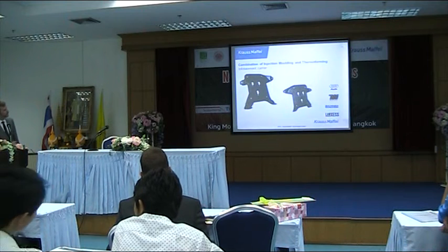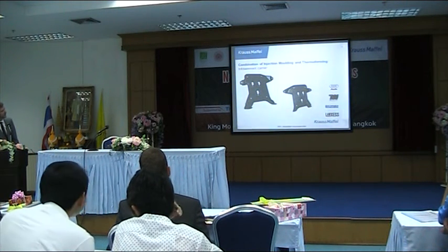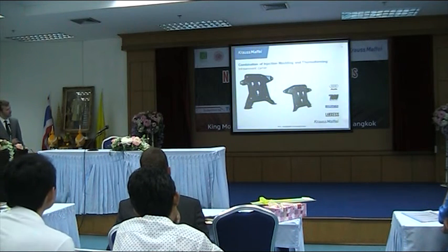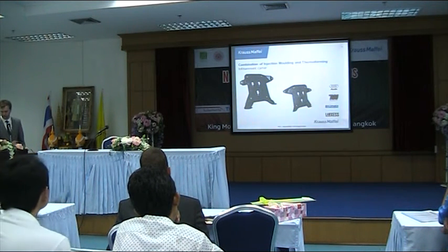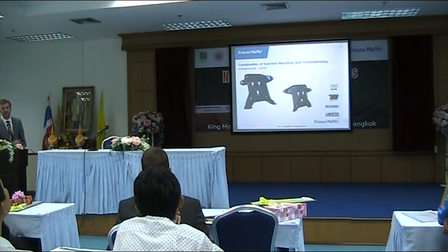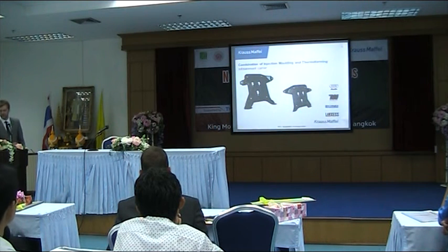It has two organic sheets. Maybe you can't see it very clearly, but you'll see it later. And you have the reinforcements on the back. They are all injection molded. The most interesting thing is that the part is not cheaper. It's even more expensive in production costs, but it reduces a lot of other costs, for example assembly, because of the function integration.